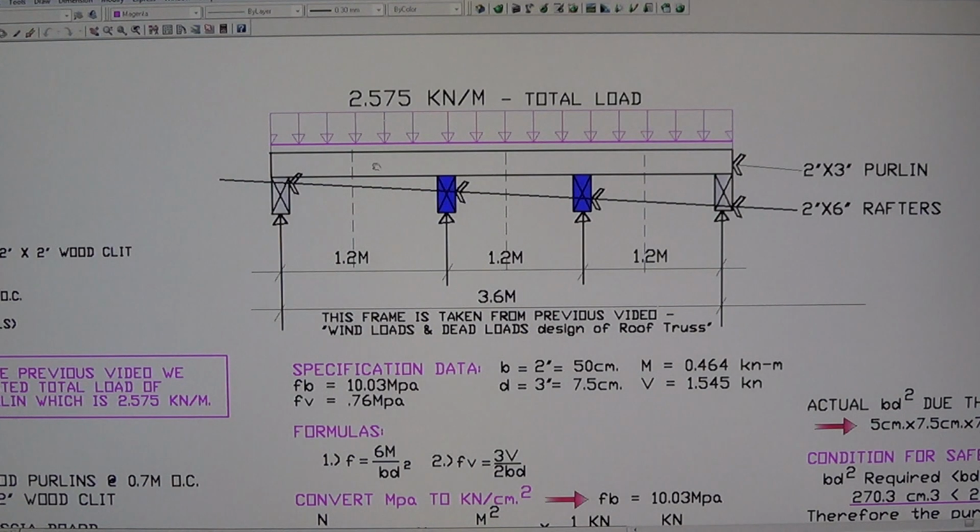There are more Purlins on the roof, but when you design, you have to look at the sizes of the Purlin, especially the length. You have to look at the commercial length of the wood, and this is 3.6. So I use this 3.6. This is 12 feet long, and that's why there are rafters there.